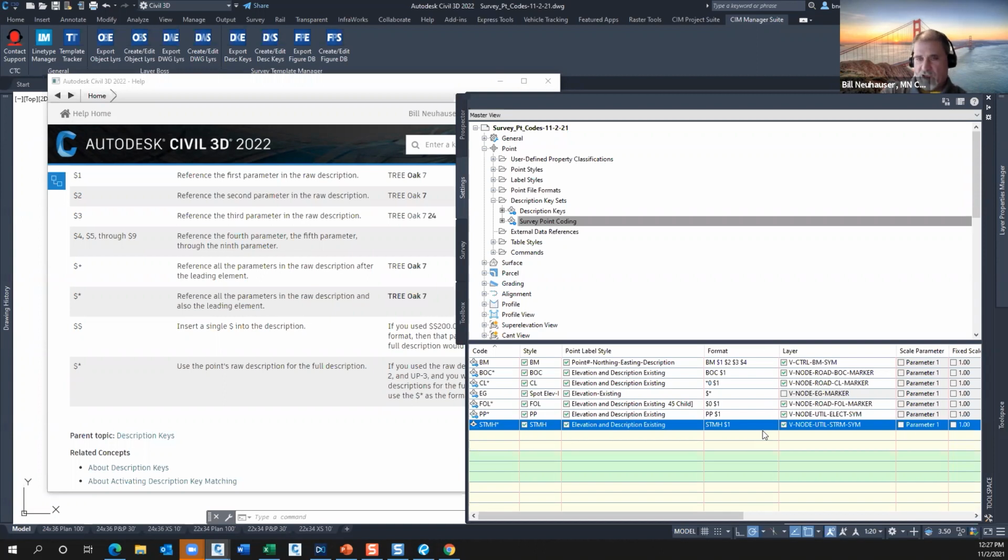We've got three options here. When we insert that manhole detail as a block in our drawing, we can either put it on layer 0, layer A, or layer B, okay? If we put it on layer 0, the only way we can turn that block off is to turn off all those component layers. Not just one, not just two, but all of them. So we've got to figure out where they are and turn them all off. The problem with that is if we turn all of them off, we're also turning off all the other blocks that may be using those same component layers, okay? So good or bad, probably don't want that to happen.